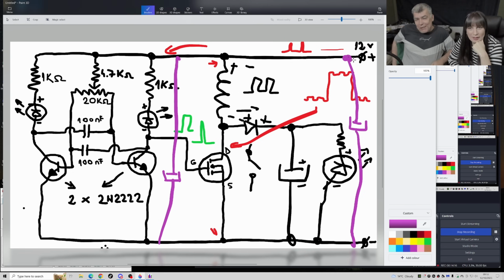Where will you put the capacitor? I will tell you. The capacitor has to be placed exactly where the noise source is, because obviously you want to cut that noise exactly at the source. And where is that noise source? Who is modulating the power line?